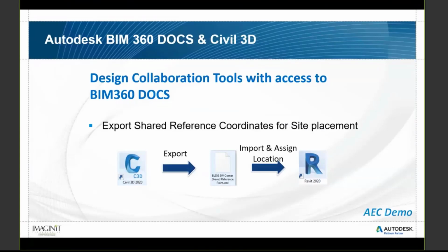And when we're looking at that process of sharing topographic information and Civil 3D data back to Revit, the next piece that is recommended would be to generate a shared reference point coordinate. Shared reference point coordinates help Revit resolve that 20-mile limitation that it has within the models. Civil 3D drawings are set up with world coordinate systems that are generally not near the origin point. And within Revit, model limitations don't allow it to see data beyond like a 20-mile range.